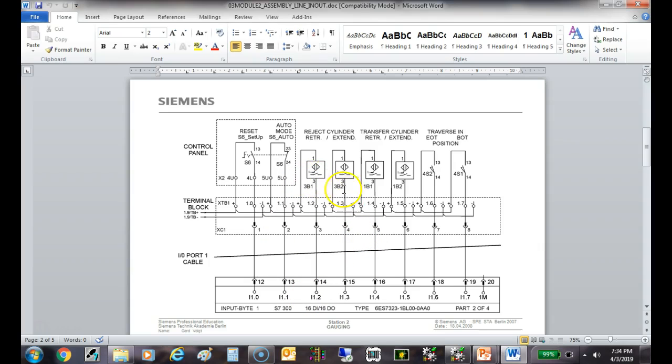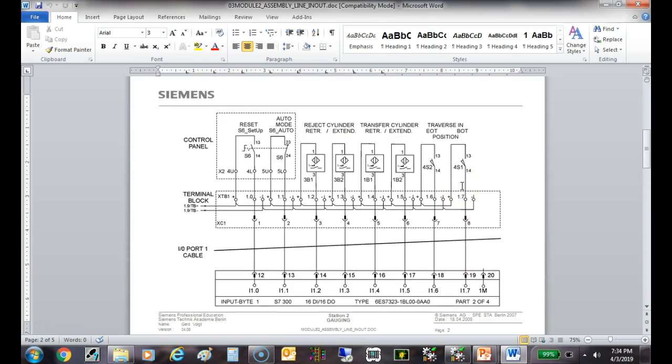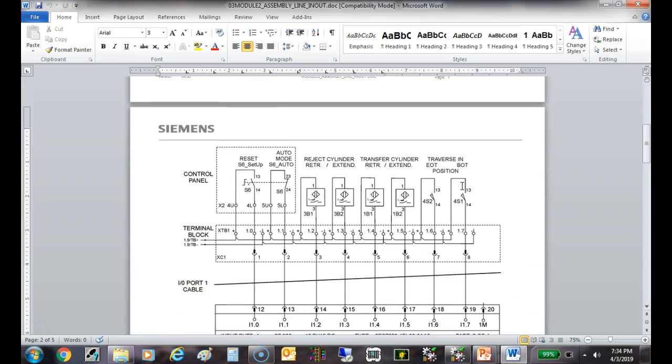This is the way you're going to be able to tell the difference between a Hall effect sensor and a reed switch. A reed switch only has 2 wires. And so it's powering up through the load itself, right? In fact, it doesn't really require any power. But this switches us around, so notice 1 goes back to plus, and 3, which would be a blue wire, is now your signal wire. So this is going to swap around.